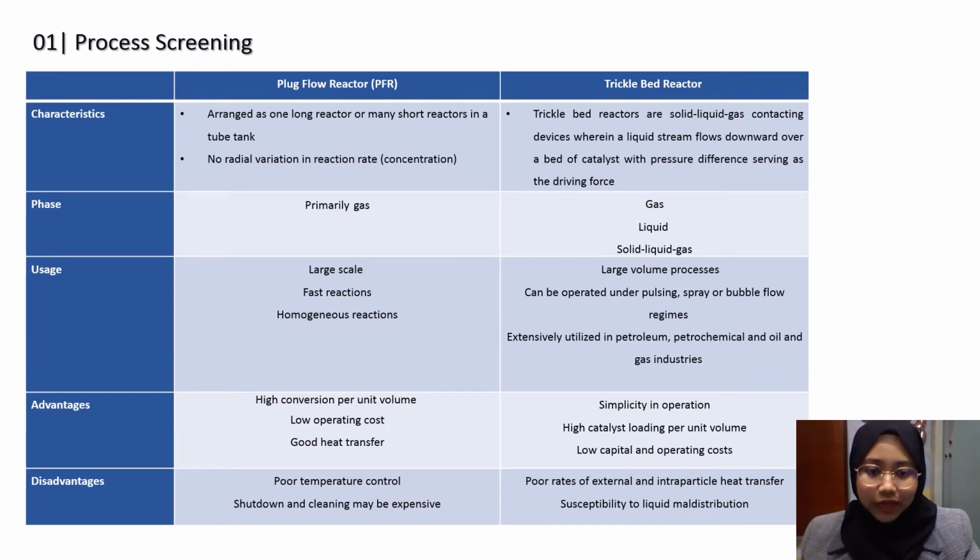The usage of catalyst is required for hydrocracking and hydrofining. The PFR is therefore chosen since it can be used for long-term use with the catalyst. In hydrotreating processes, catalysts like cobalt molybdenum or nickel molybdenum can be used.